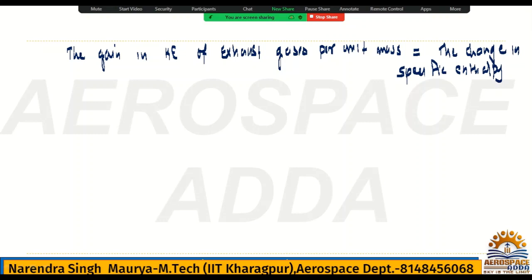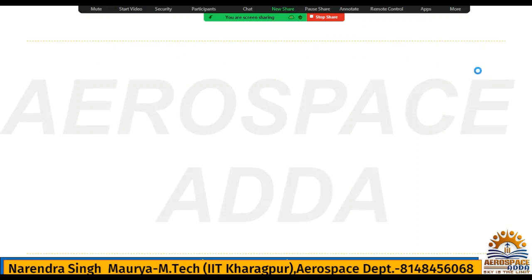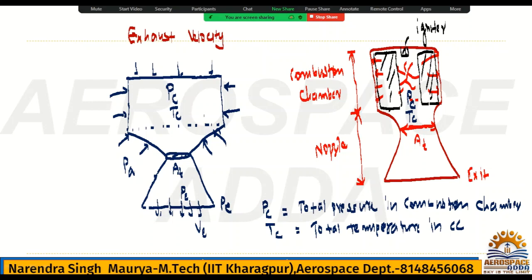How to get that? What is the change in specific enthalpy? See, we have total temperature Tc, okay, and this is the exit, and obviously the exit will have a static temperature. So this Tc will be the total temperature. I told you total temperature you can write as T naught, and this total temperature will be constant throughout the nozzle, because it is a very basic principle. I have repeated many times, and now also I am going to repeat. In nozzle and diffuser, total temperature must be constant. It is not going to change.